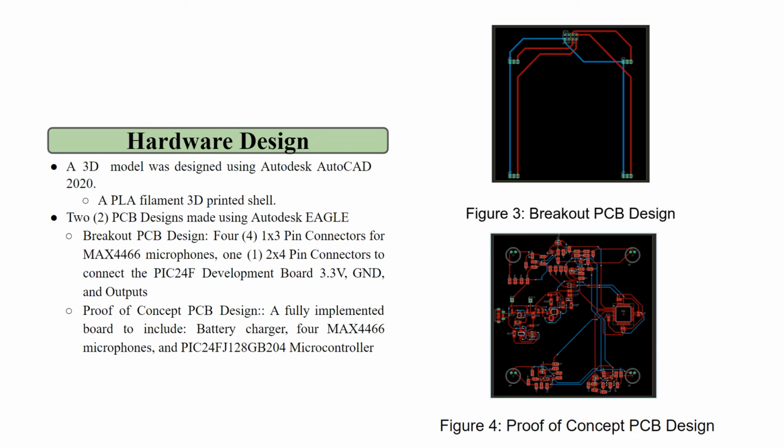A breakout PCB design that would use pin connectors to establish a connection to the PCB. This breakout PCB design would include 4 1x3 pin connectors for the MAX 4466 microphones and 1 2x4 pin connector to connect the PIC24F development board to the 3.3 volts, the ground, and the outputs of the microphones.